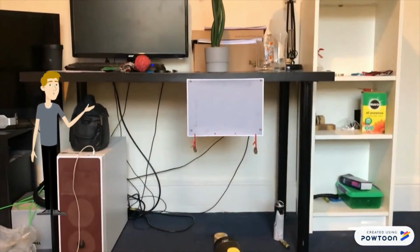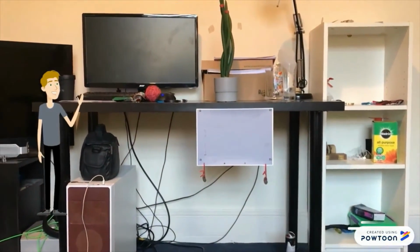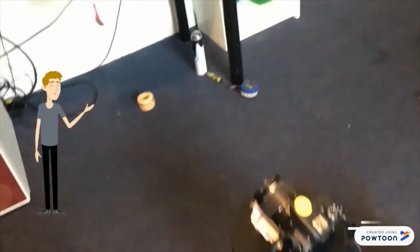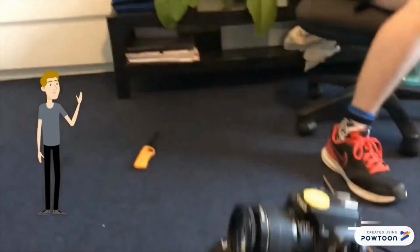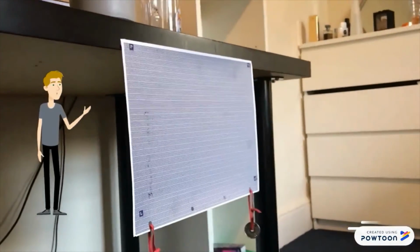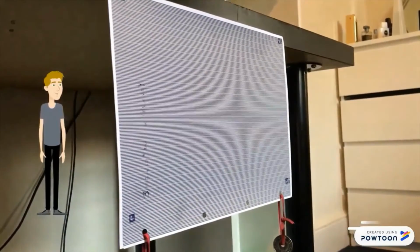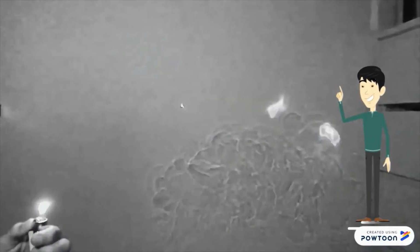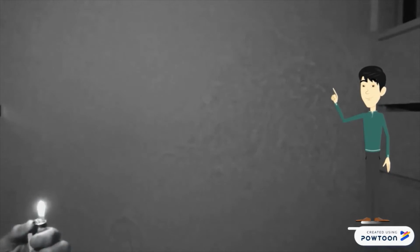This is our Schlieren setup. It's made up of a piece of A4 paper with inkjet printed lines at a fixed distance of 80 cm from the DSLR camera, on top of a makeshift stand to keep it stable. This was all within a low-lit room so that there isn't any excess light interacting with the system. With our apparatus in place, we closed the curtains and we were ready to film some Schlieren imaging effects.